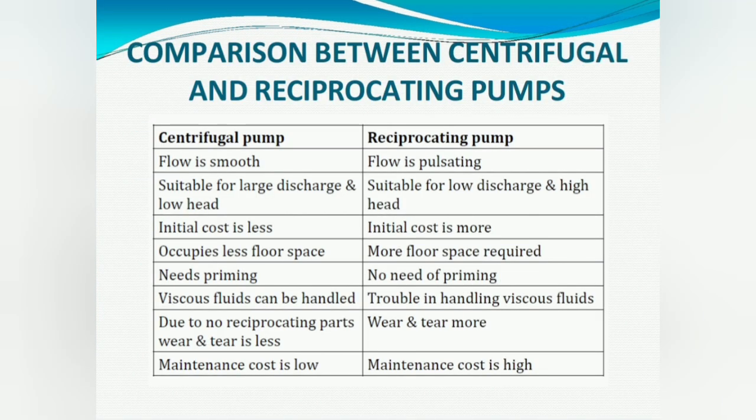Now we can do a comparison between these both types of pump, centrifugal and reciprocating pump. In case of centrifugal pump, the flow is smooth and the flow is pulsating for reciprocating. Centrifugal is suitable for large discharge and low head, whereas reciprocating is suitable for low discharge and high head. The initial cost is low for centrifugal, it is high for reciprocating. Centrifugal occupies less floor space and the other occupies more floor space.